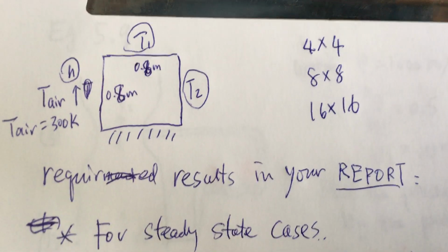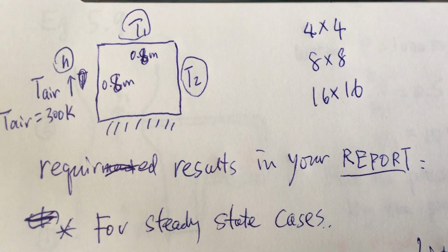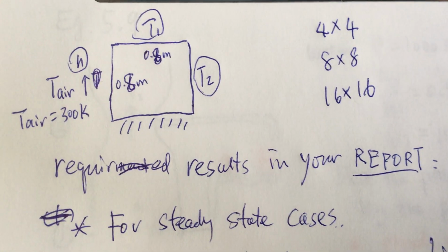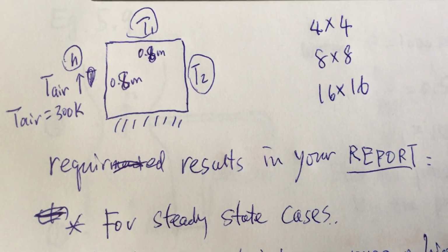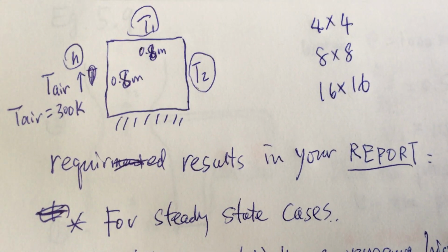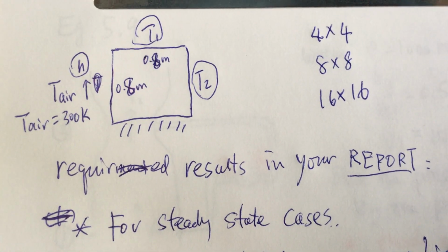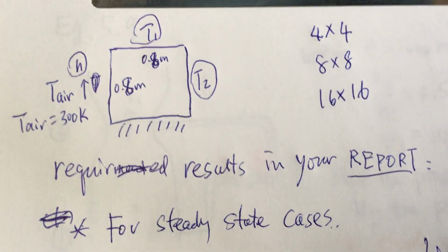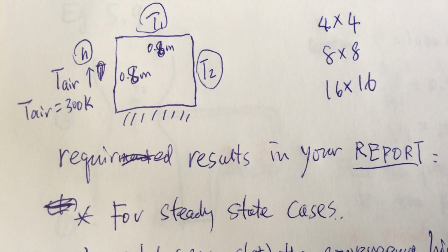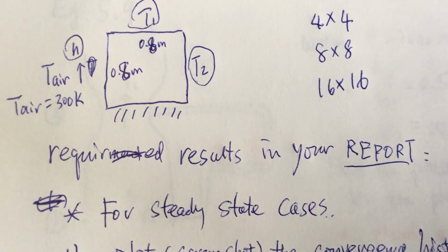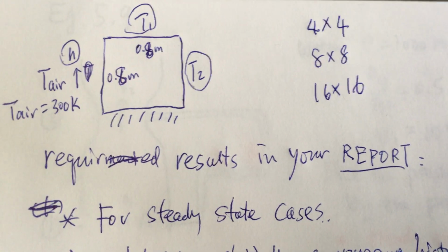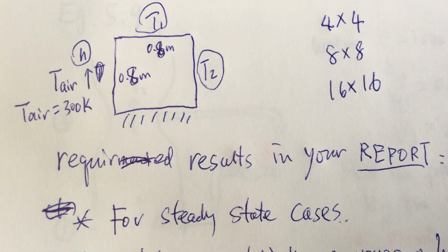So always, as a CFD engineer, when you do a simulation you want to know what grid size is appropriate. You don't want too many grids, because it will slow down your calculation and your simulation, since all the equations need to be calculated on every grid point.